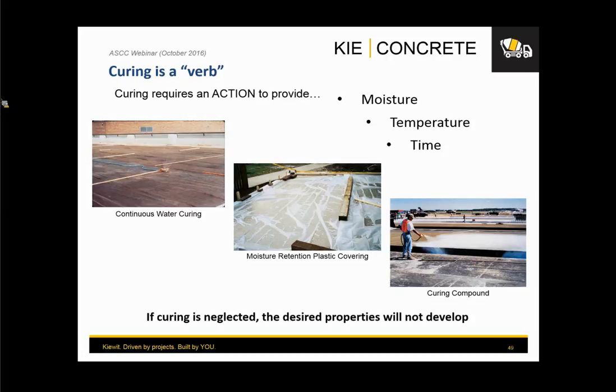However, you think about providing some level of protection from rapid evaporation, because that's going to allow rapid drying shrinkage cracking too, right? So it's all about the application, the exposure, the conditions, and then what type of operations are also coming through that are going to affect the process that you're going to implement, because all of them can provide you a good product. I don't want to pick on one or the other. I don't want to say this is best, this is not good, right? All of them have a place, and all of them are going to allow you to get good concrete. It's just making sure that you understand what's going to be the purpose of the use of the structure and that you understand the exposure. And that's going to allow you to then get a better selection on what to pick for a curing method.